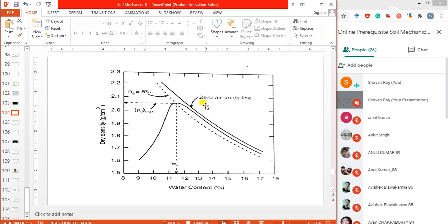After the optimum water content is reached, the air voids approach approximately a constant value, as a further increase in water content does not cause any appreciable decrease in them, even though a more orderly arrangement of particles may exist at higher water contents. The total voids due to water and air combination go on increasing with increasing water content beyond the optimum, and hence the dry density of the soil falls. So this is basically the physics which normally happens in the soil particles when we add water to soil particles.